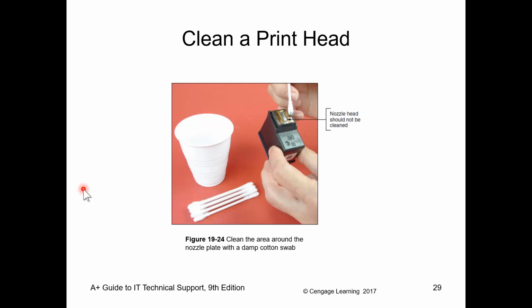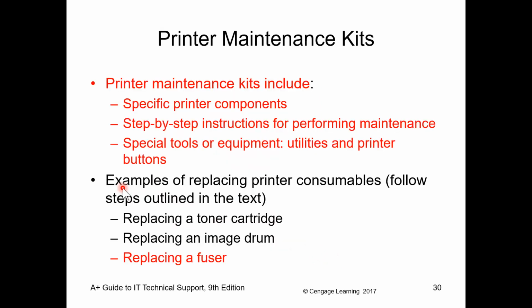Inkjet printers have a cleaning process. They have a little sponge inside them that it wipes the head on to get any excess ink off of. If the head is not coming clean, you can use a Q-tip and some alcohol. Like on my Epson 2750, it has a clean cycle I can run it through, or it has a deep cleaning cycle. I had to run the deep cleaning cycle on it recently because I wasn't getting color out of the printer.